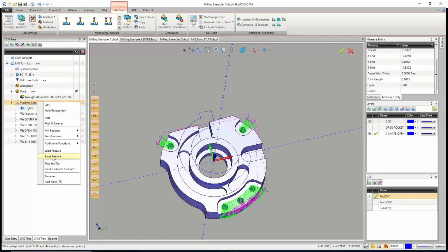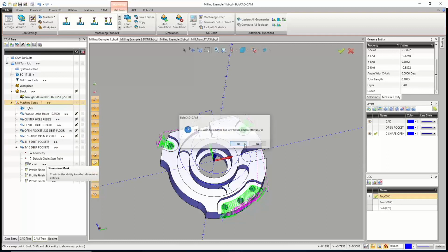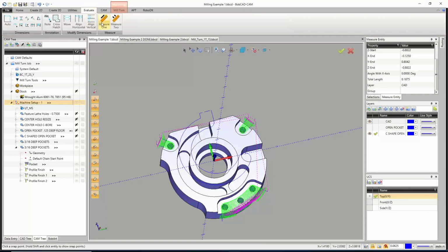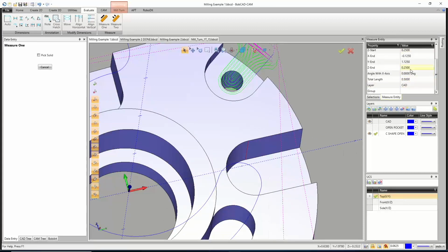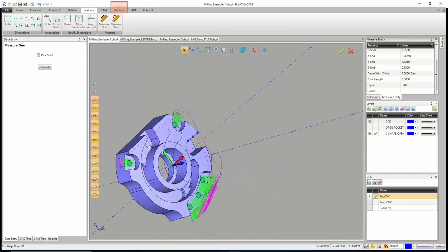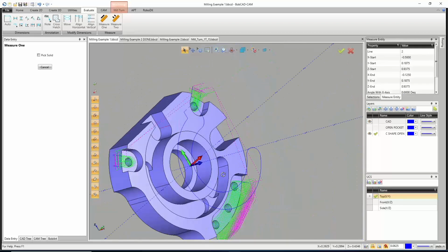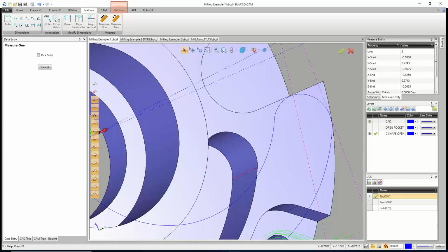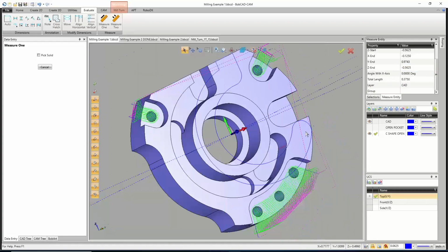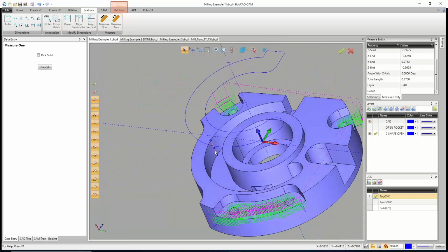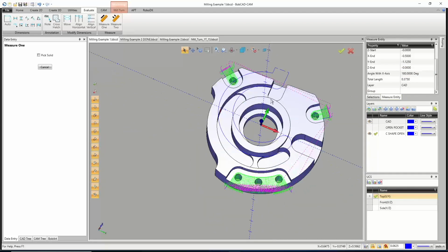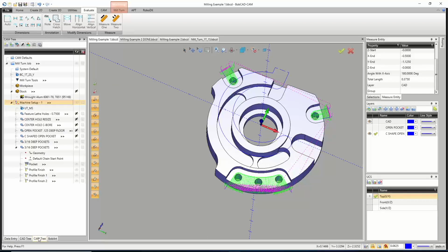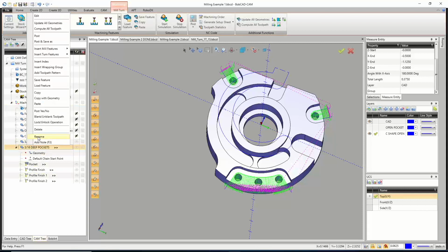So I'll go ahead and paste my feature, and yes, I want to take some measurements of this one, and so we'll see this depth for that pocket there is a 1/2 inch. Whoops, right there. We'll see that this one over here is also a 1/2 inch. The pocket on the inside of this is 3/8, and I believe this floor is also 3/8. Let's look. Also 3/8. So we're going to have 2 more pockets. One here that goes to that 1/2 inch deep, and then these 2 will be their 3/8. So I'll go ahead and do the 3/8 ones first because it's a quicker rename.